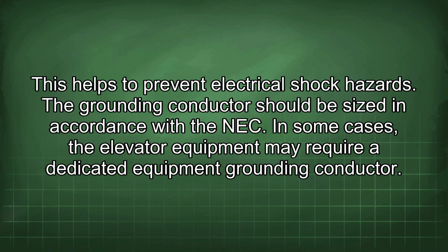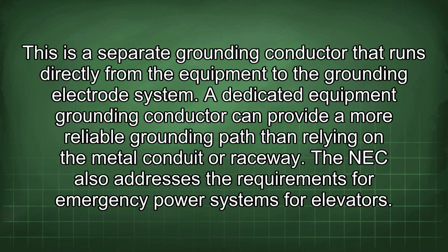In some cases, the elevator equipment may require a dedicated equipment grounding conductor. This is a separate grounding conductor that runs directly from the equipment to the grounding electrode system. A dedicated equipment grounding conductor can provide a more reliable grounding path than relying on a metal conduit or raceway.